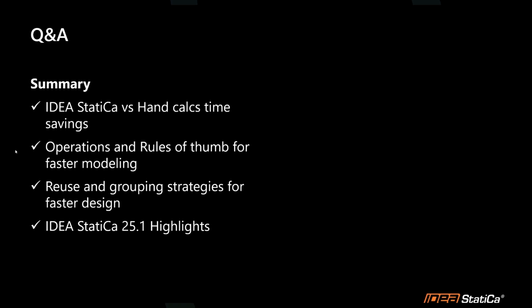Johan, there's a question here about is bolt prying effect considered in the analysis? You want to answer that one? Yep, definitely. So here within IDEA StatiCa, those limit states are essentially checked within the FEA analysis. Basically, if you have a connection with lower stiffness compared to a connection with higher stiffness, you will be bound to see those effects of prying actions in a connection with a lower stiffness.